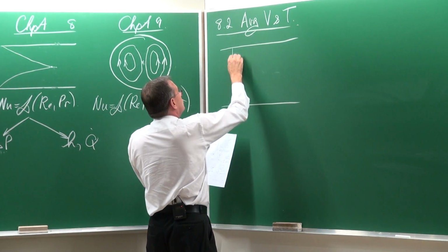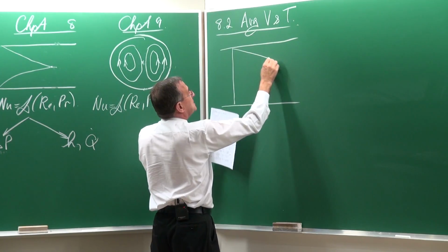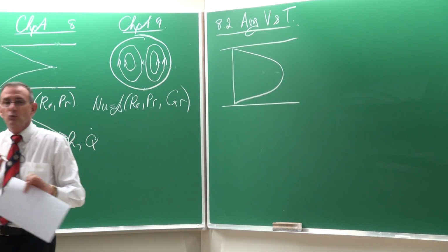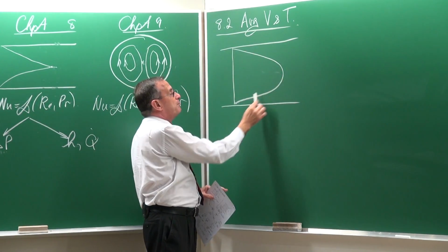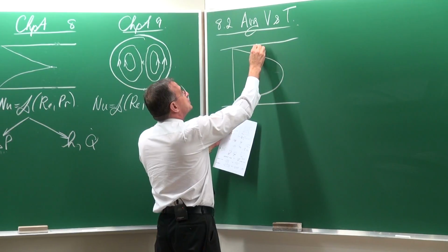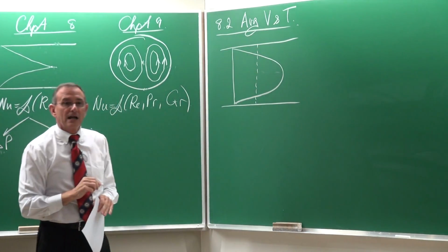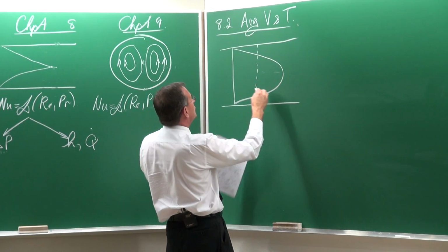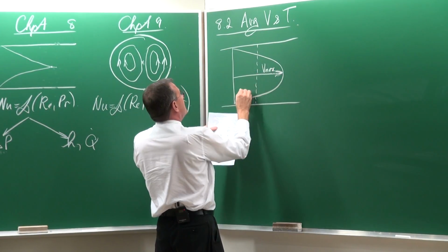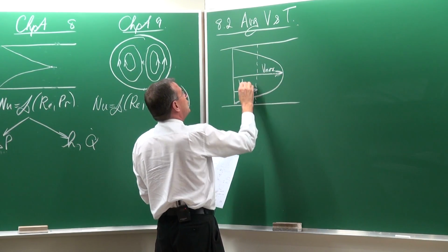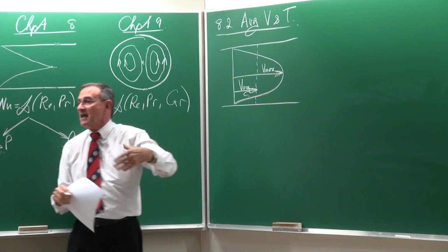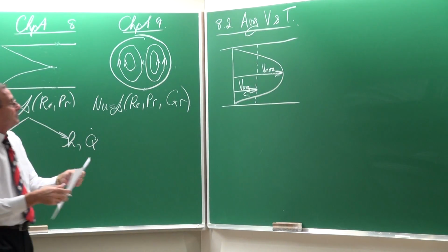What we are normally going to do is, although we know that there's a velocity gradient there on the inside, if it's a circular tube and the flow is laminar, then that would be a parabolic velocity profile. Now, to make things easier, although we know the details of this velocity profile will develop so that that velocity is Vmax, and this velocity is V average, and the maximum velocity is actually 2 times the average velocity.